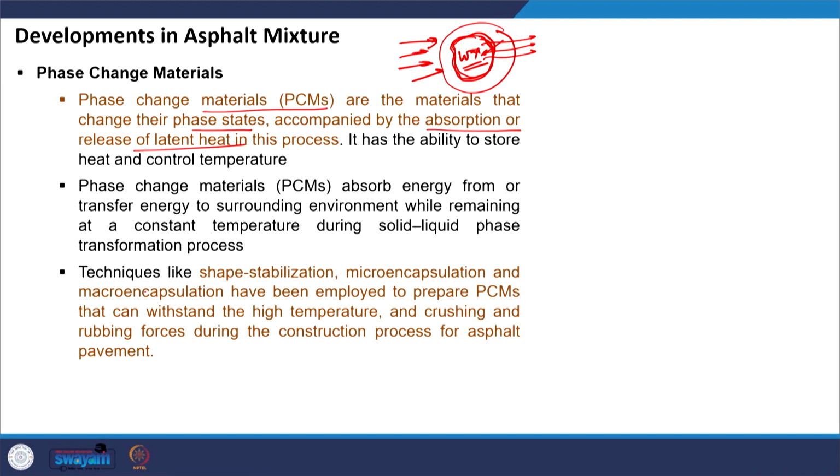So, various types of PCMs have been experimented with in asphalt mixtures. People have tried techniques like shape stabilization and micro encapsulation, wherein the PCMs are kept in a very small encapsulated form, just like fillers. They can also be incorporated in the form of macro encapsulation, say like an aggregate system, okay.